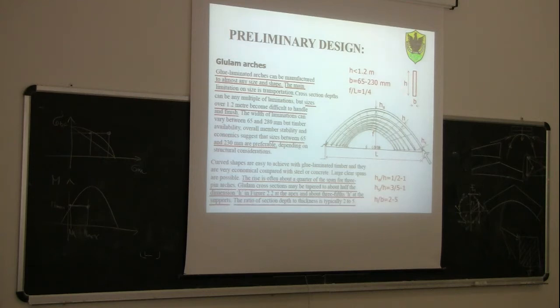Also, the depth of the arch divided by the breadth of the arch should be 2 to 5. So those are just some numbers that are useful when we do the preliminary design of our structure.